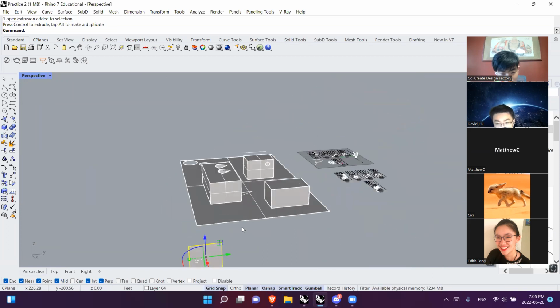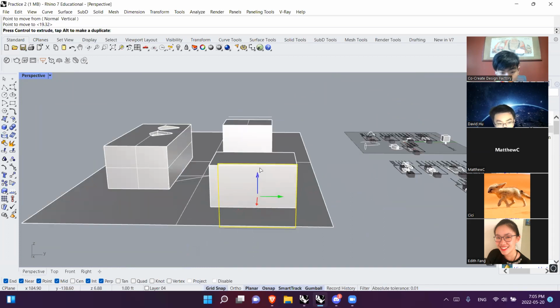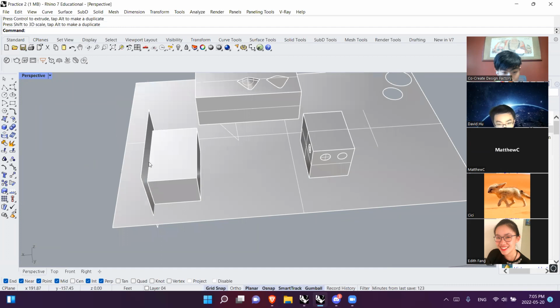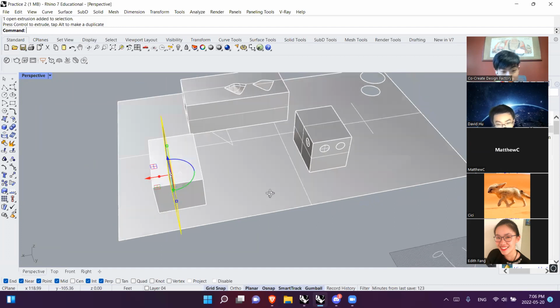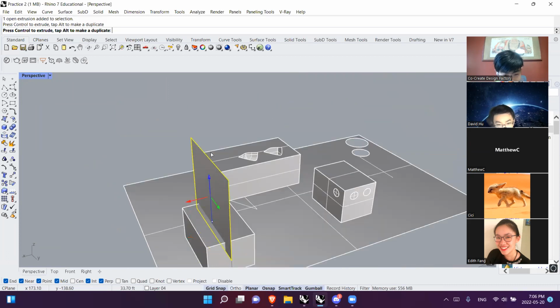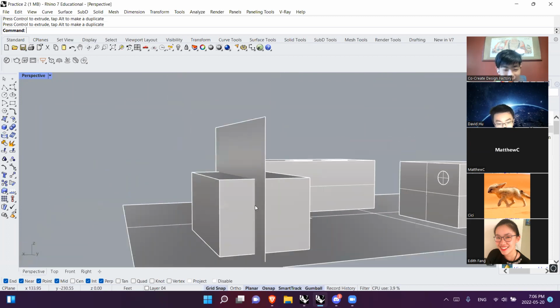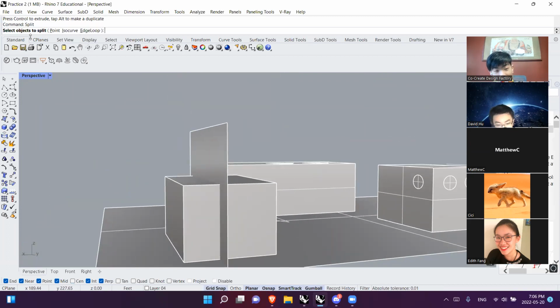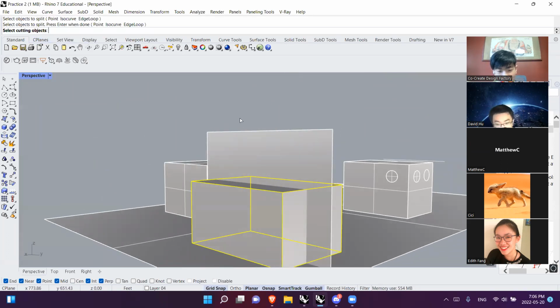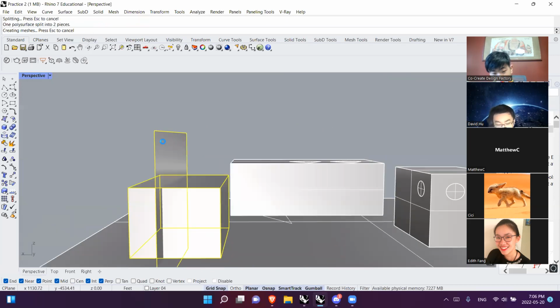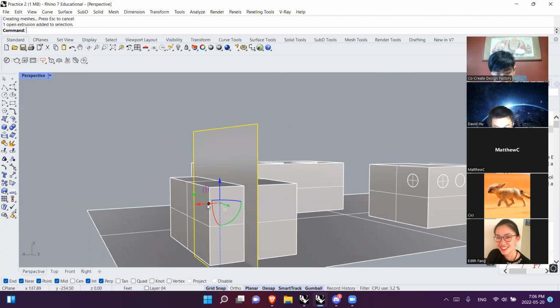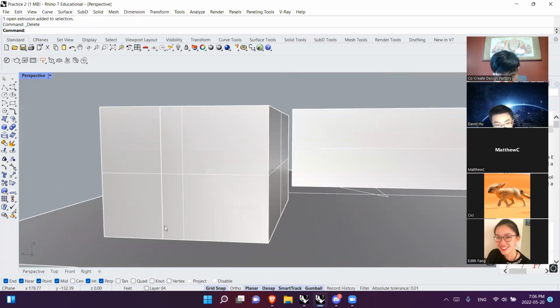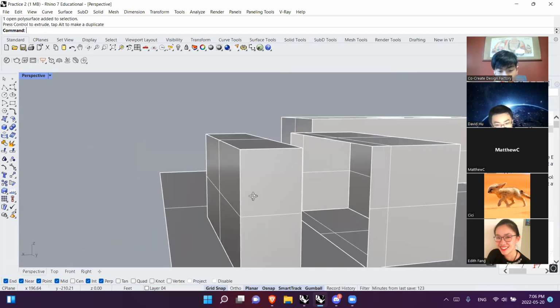Let's make it bigger. Oops, why is it over there? Move it here. Okay, make it a lot bigger actually. So you have your knife here, which is just a surface plane rotated, and then a very cool visualization: you cut this in half. This is executed by doing the split command. Use object to split. That's your object to split. Enter. And your cutting object is your knife, which, well, this looks like a knife. Click that, enter. Now you can see, if you delete the knife, see how it left this mark here, right? And these are 2 separate surfaces.